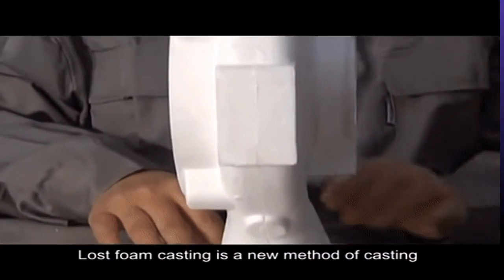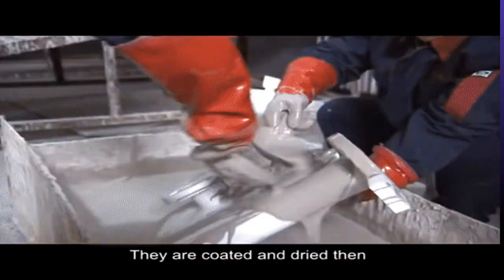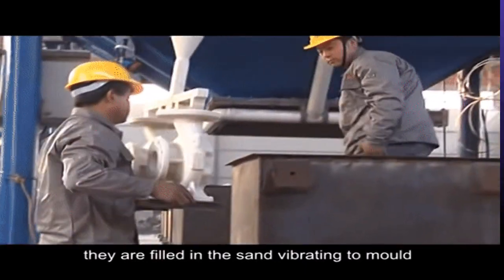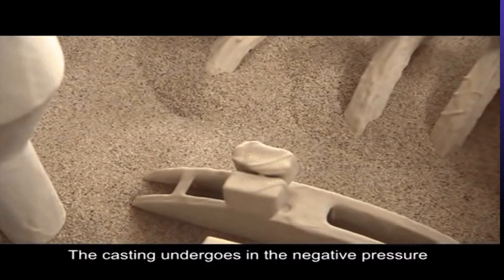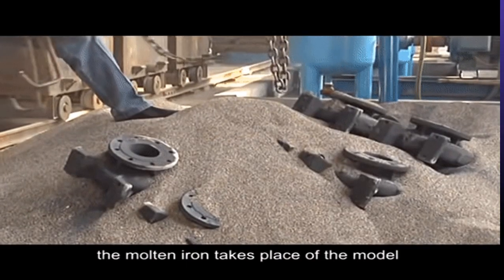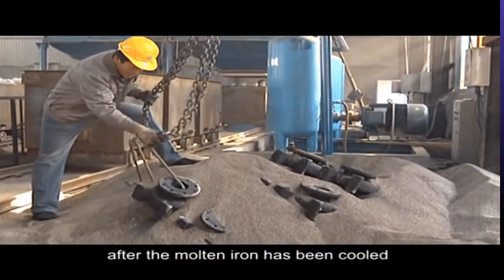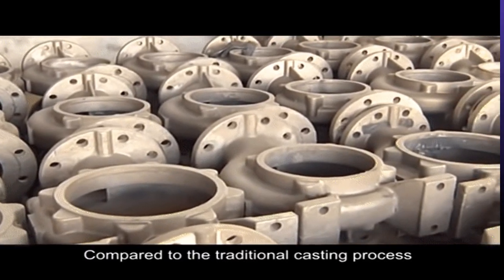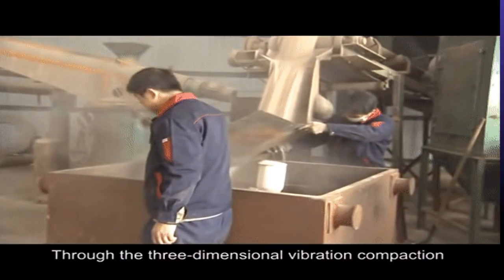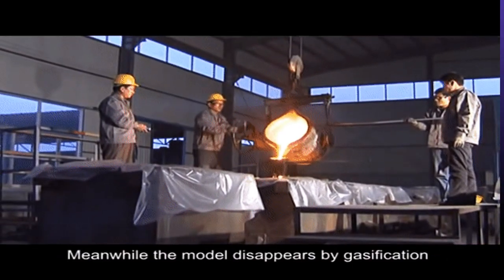In the evaporative pattern casting process, the pattern is made from polystyrene, which evaporates after contact with the molten metal to form the cavity for the casting. The polystyrene pattern is formed with the use of metal mold methods and is then supported with refractory material, packed within the flask with sand to support it. Upon contact with the pouring molten metal, the polystyrene evaporates and the cavity is filled with the molten metal, which is slowly cooled down and solidifies.